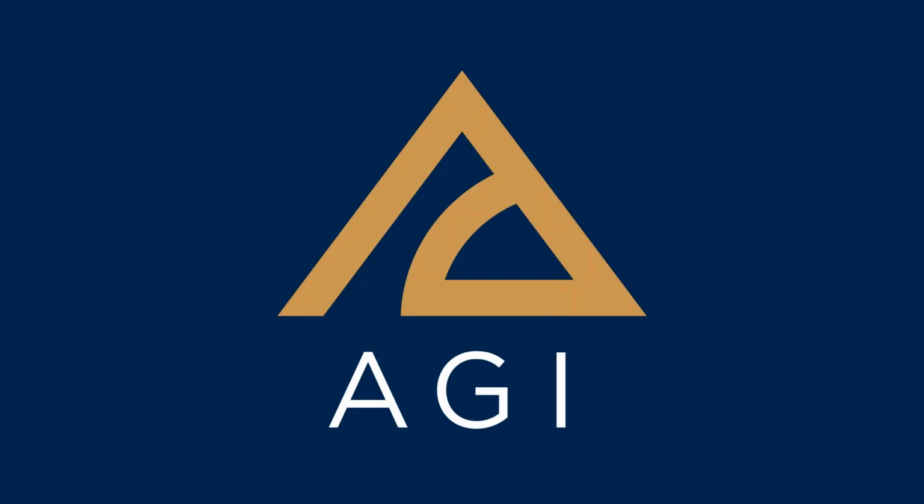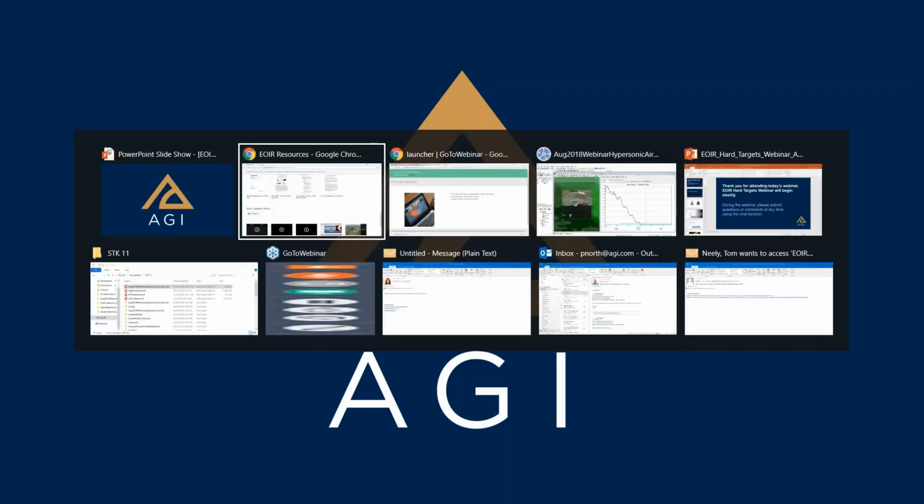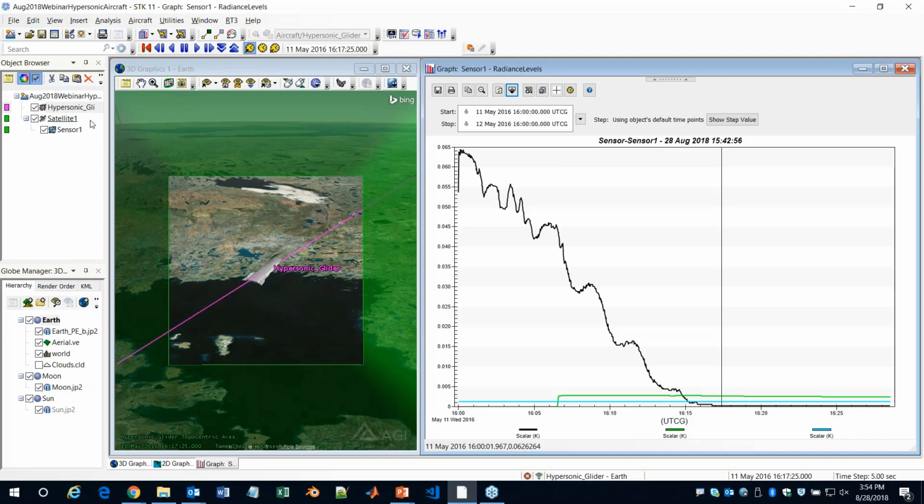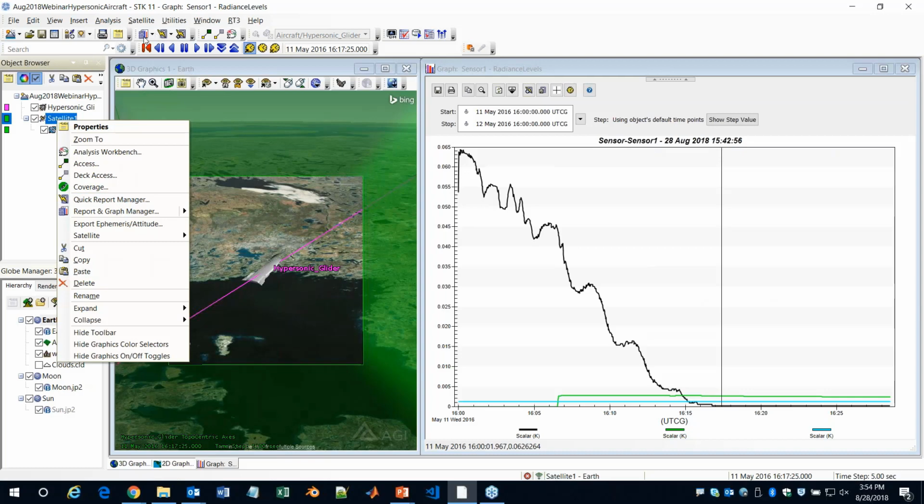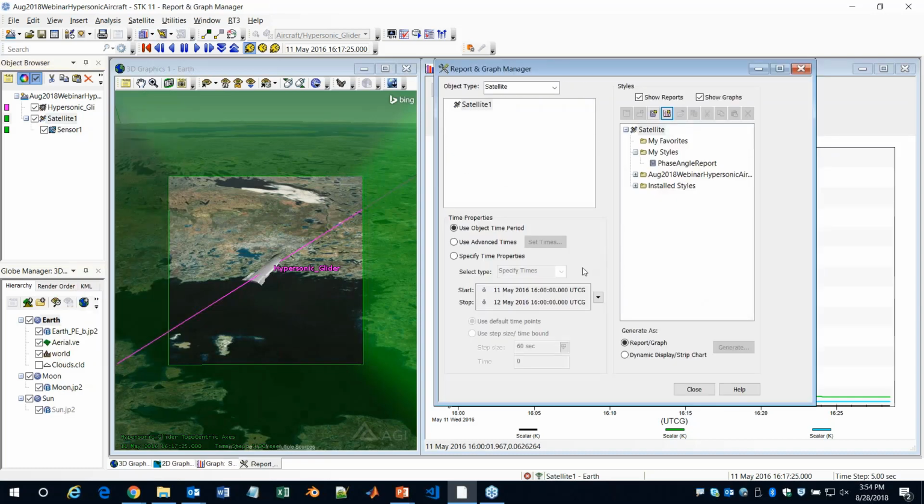Me and MATLAB. It's the time temperature profile, and I believe they're referring to the CubeSat lesson. Got it. So with the CubeSats, I'll actually use this as an example. You can generate a thermal profile a number of different ways. For example, for the temperature map, I used MATLAB to do the conversion to reflectance, add the passive thermal model to heat it up to the right temperature at the different times of day, and then I added my own hotspot. It uses a Gaussian model and a Poisson distribution to add some heat to different ground regions.